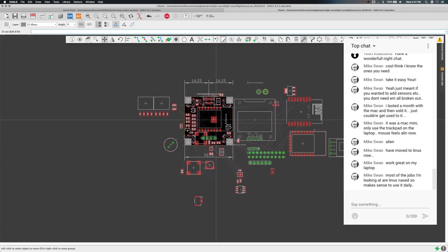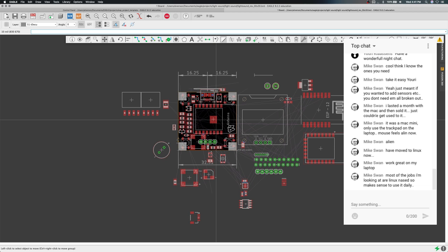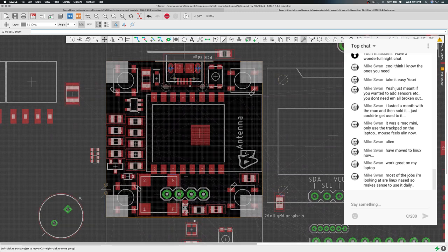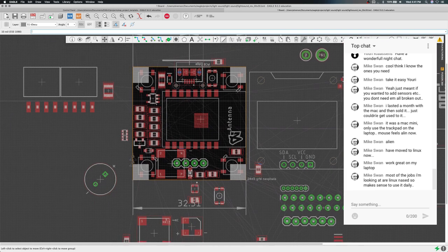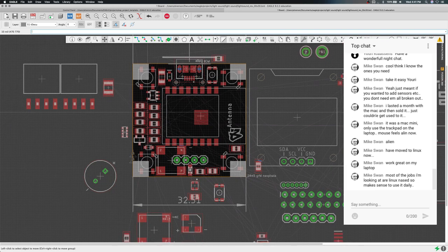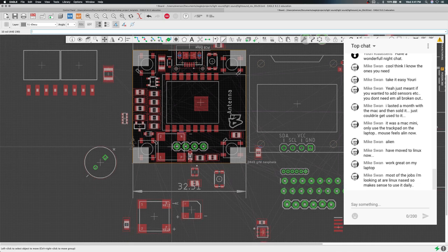So you can see this is like a sketchbook. I just got a bunch of stuff on here. These little tiny LCDs also match this footprint, and it fits on my other board perfectly, but it's not really going to fit on this one. But you can still use it for something. So that's kind of where I'm at. Whether I'm going to be able to route it or not, I might have to drop the size of all these components. And I think this 7mm buzzer is going to be plenty loud.